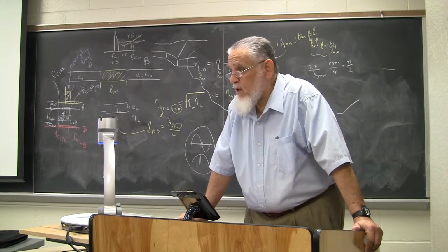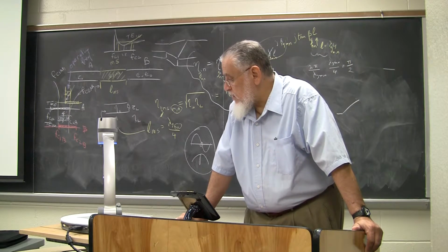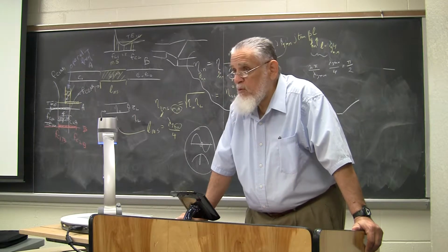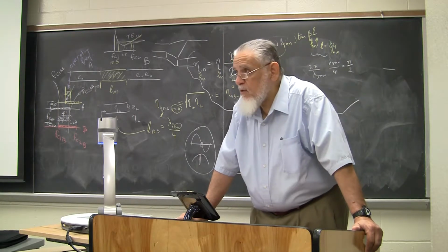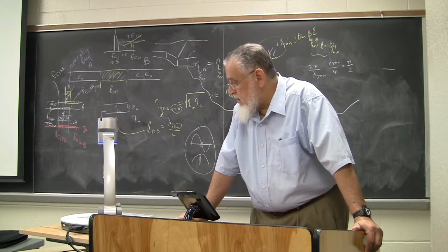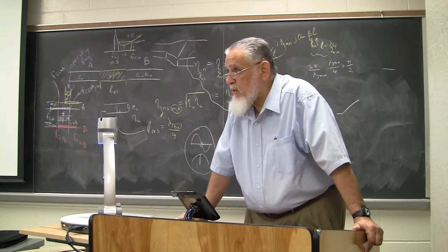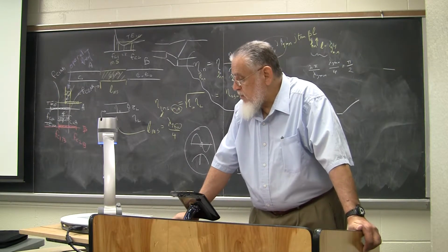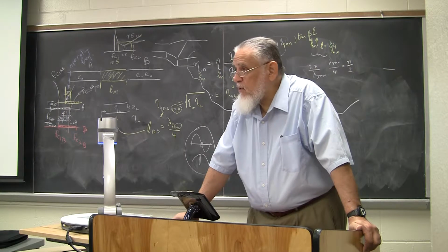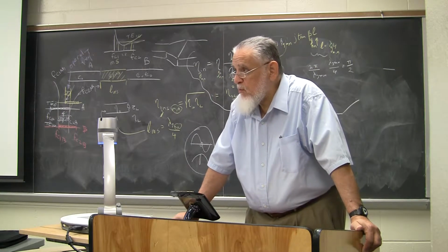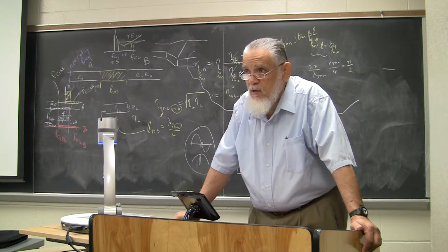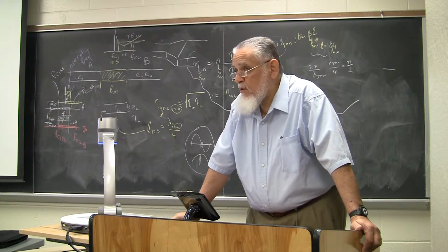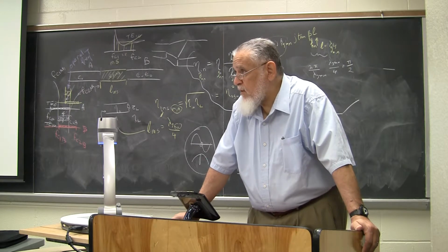The center conductor becomes a thin strip. As you can see, we are showing it as width W. Typically, it has a thickness, referred to as T. In the analysis, usually it gets neglected, but if you want to do a better analysis, you have to account for the thickness of that conductor, because that thickness not only controls the field distribution, but also controls the evaluation of the losses, because that thickness eventually controls the resistance of that strip.